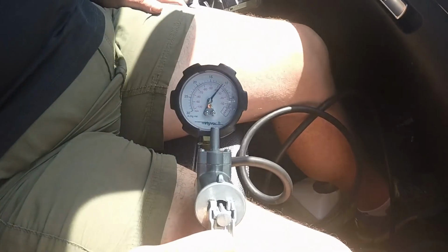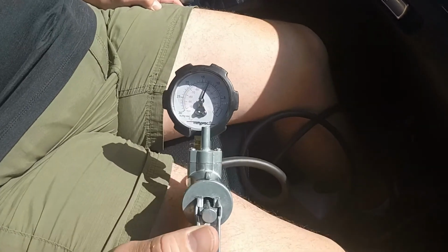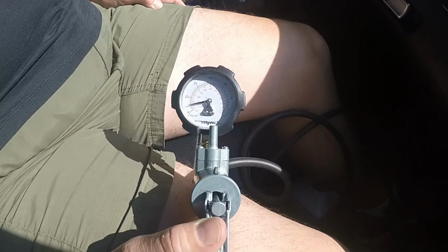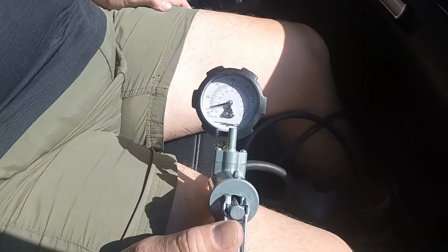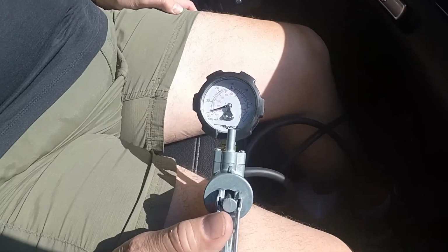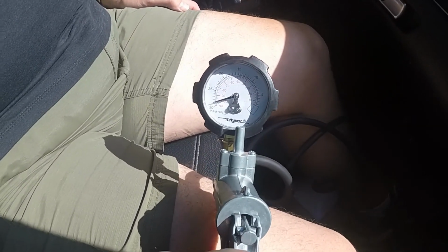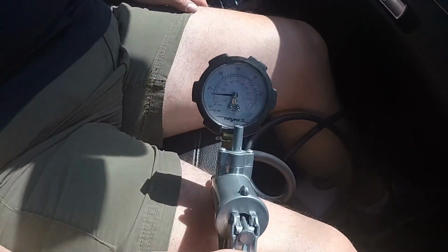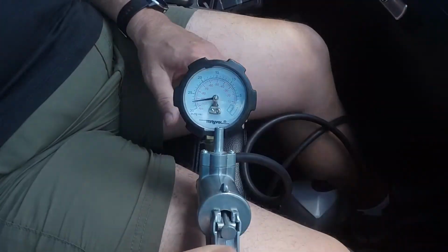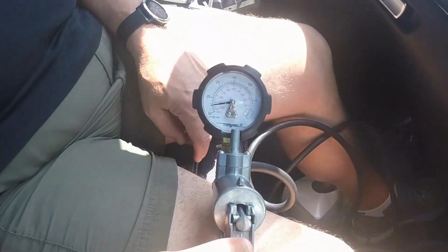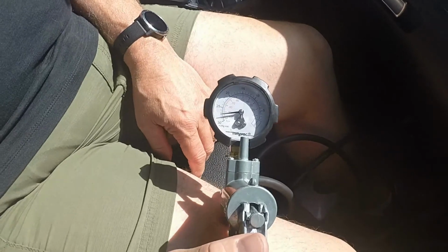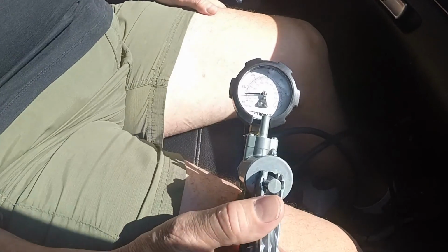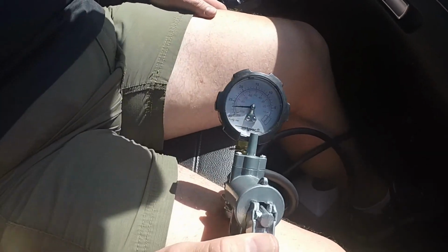But what we're going to do is take the car out and just hammer it and watch. Whoa, there the solenoid just tripped. And now that the wastegates are blocked off, look how much vacuum this pump is making. So it looks to me like we definitely have a leak on the turbocharger side of the vacuum control solenoid. And just to be clear what's happening here, when the code sets, the computer shuts the solenoid off and then we can see how much vacuum the pump is actually producing. So we've got a leak on the turbocharger side of the solenoid.